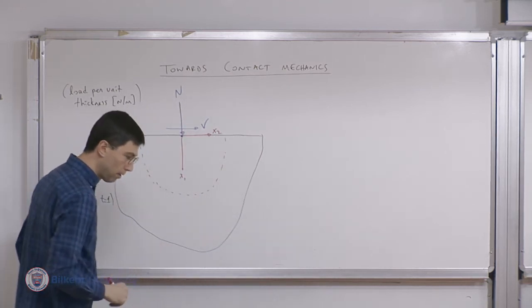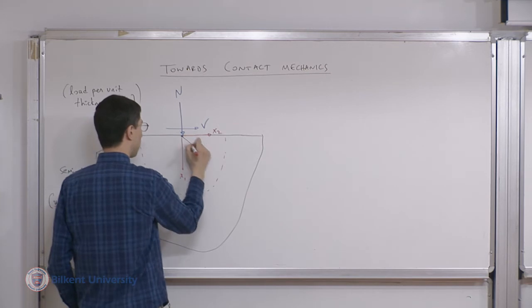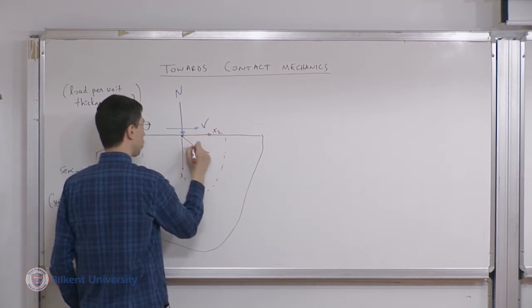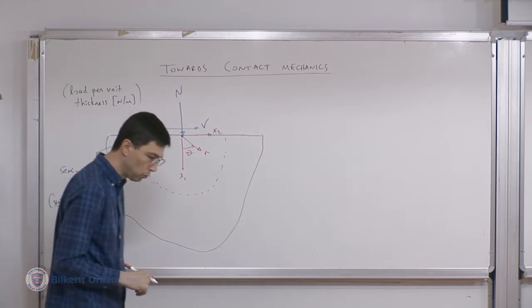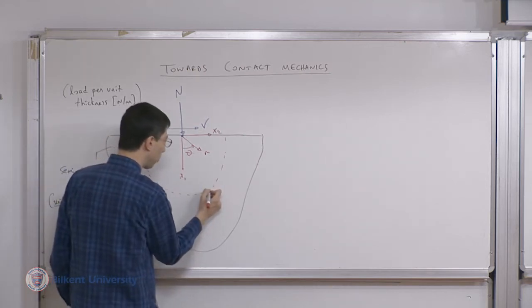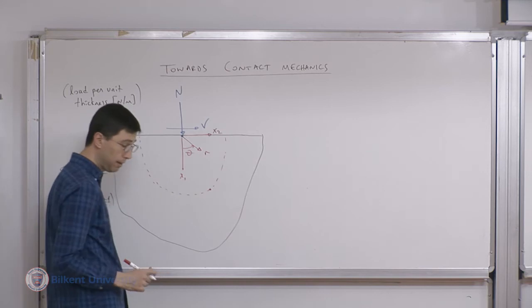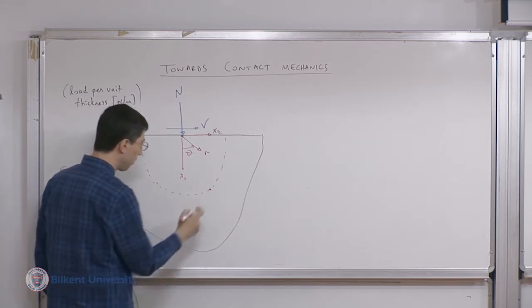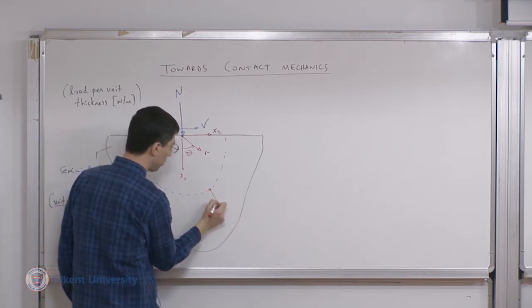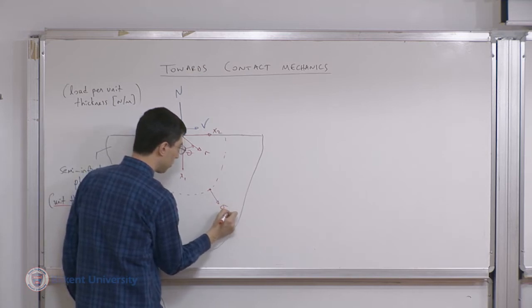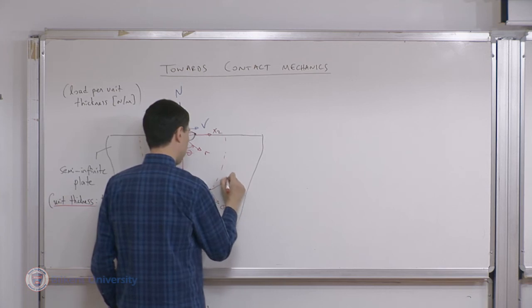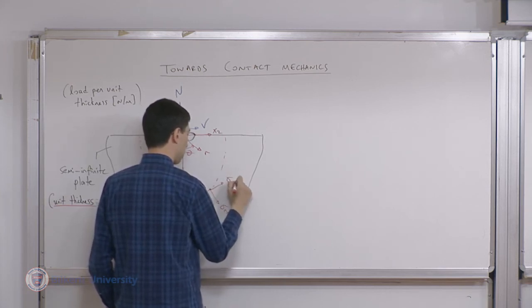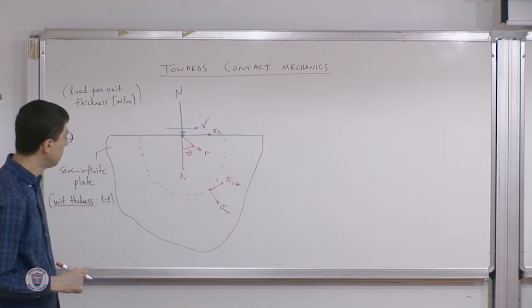So that will eventually be the radial position, and the angle is as usual with respect to x1. So if I look at any point in a cylindrical coordinate system, there will be two stresses here. There will be a sigma rr, and there will be a sigma on the plane with normal r in the direction theta, sigma r theta.